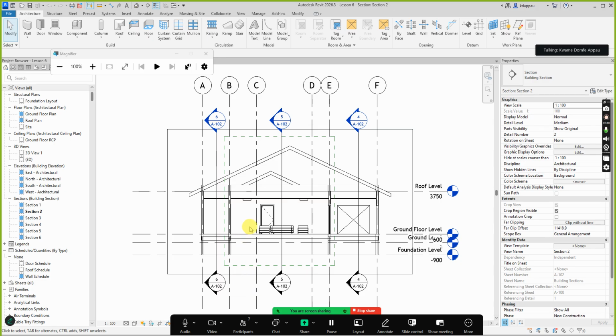So the discussion today is on editing elements. If you want to create any custom objects, which is a requirement for any Revit project, then you must be able to edit any object to behave the way you want. If you want to create a brick wall, you have to take an existing wall and edit it to have the behavior and characteristics of a brick wall.